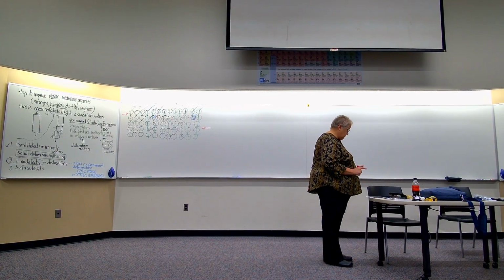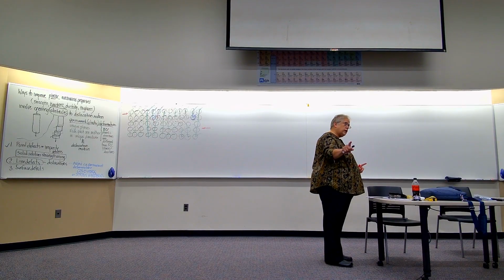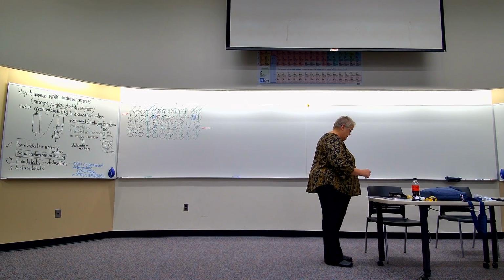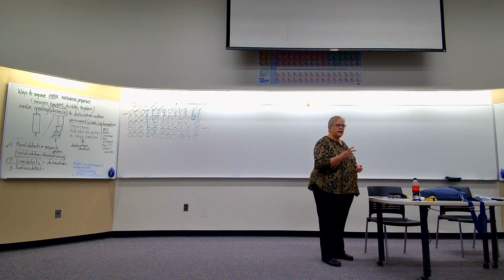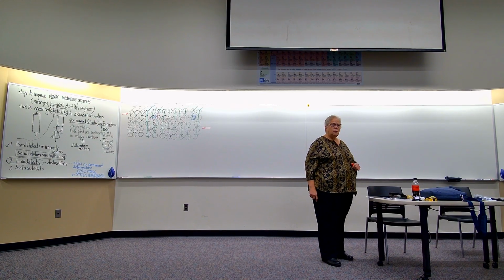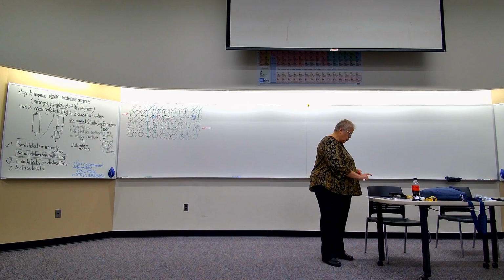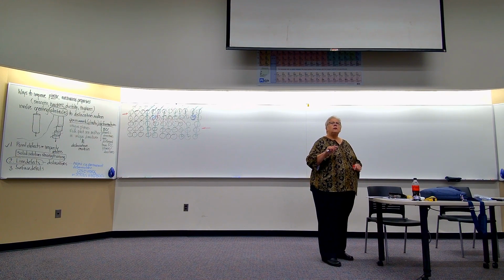First one shows, as the percent cold work increases, the yield strength, that's the left y-axis. They're both yield strength, there's just two units. The yield strength also increases. There's PSI on the left and megapascals on the right. So as percent cold work increases, strength increases.